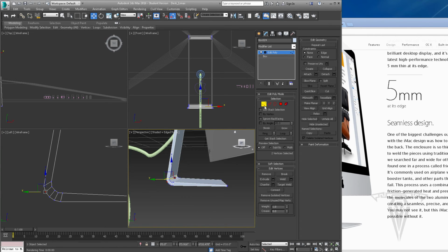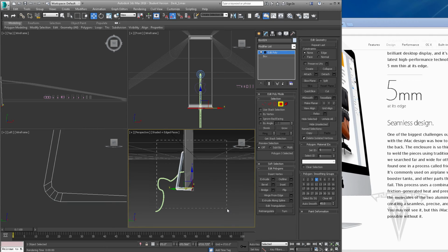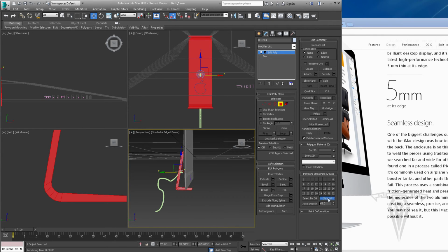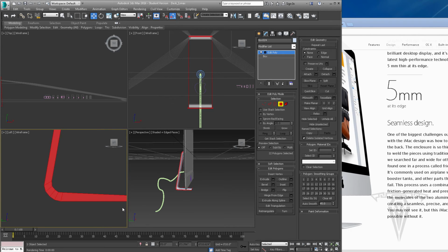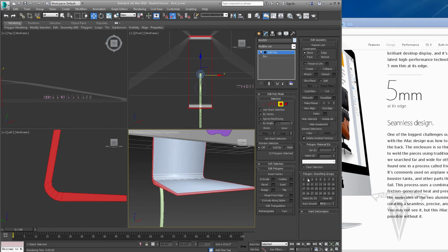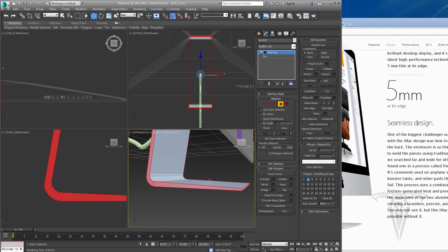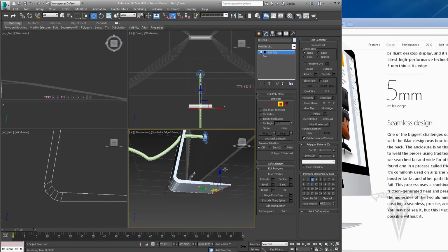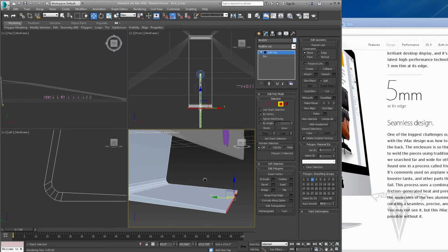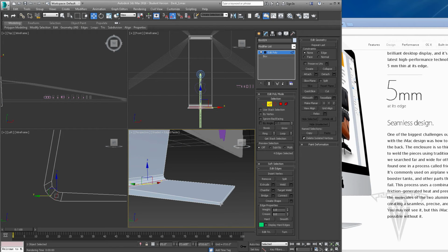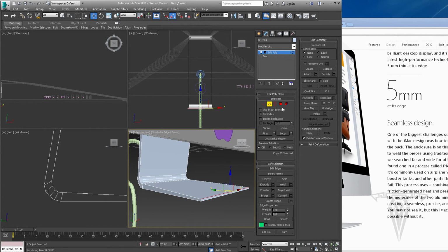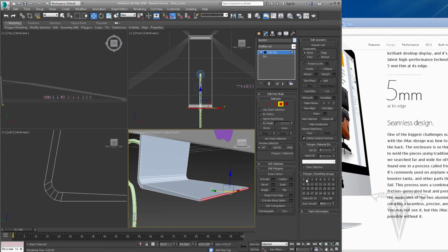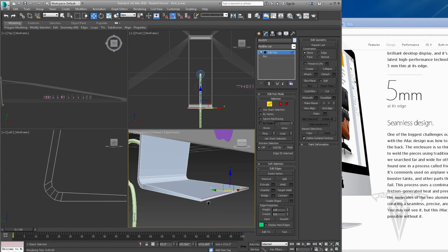Voila. Let me go ahead and select all the polygons right now and do a clear, set them all to 1. I'm going to select this polygon, hold down Shift so it loops all the way around it. Set the 2 and turn off 1. Then I'm going to select this one, set it to 3, turn off 2. Okay. So now let's go to edge mode. I need to bevel out this front edge here. In fact, actually, now that I'm thinking I have to bevel it, let me switch this one to 2 again.